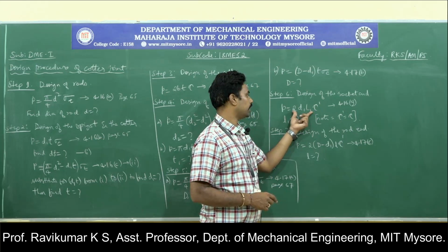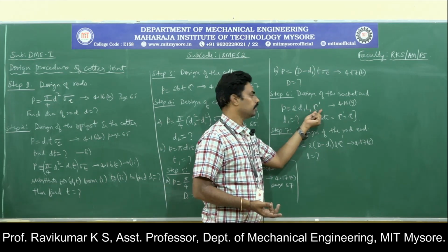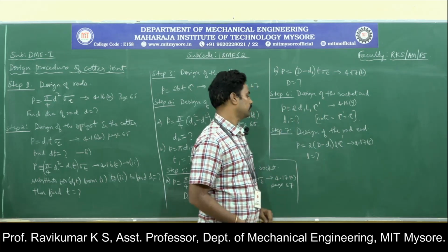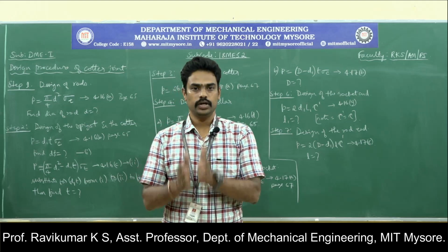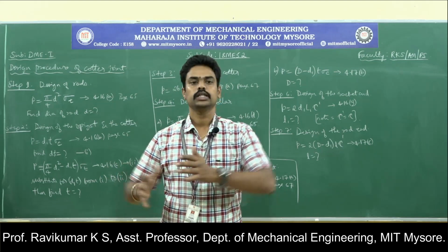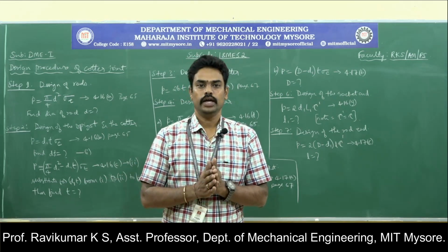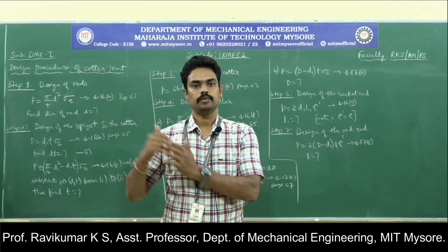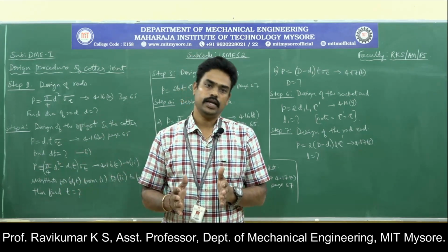So similarly, this is the area of shear. Since it is double shear, it is 2. Area of shear, stress, load. Okay. So the basic formula being P, the load, is equal to area into the stress. The type of area, if it is shear, then take the corresponding area of shear. If the type of area is tearing, that is tensile, take the tensile area.